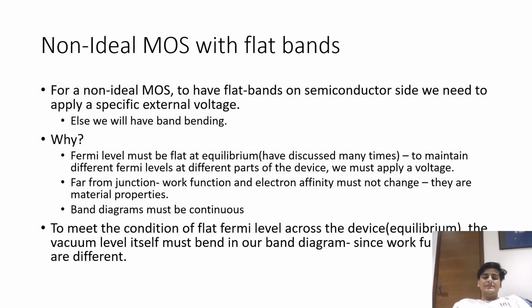Why is this the case? This is the case because if you have a low Fermi level at the metal and a high Fermi level at the semiconductor, for example, keeping a fixed vacuum level so that your phi m and phi s expressions are able to match, what that essentially indicates is that electrons are more comfortable being pulled towards the metal from the semiconductor. So essentially, there is a tendency for electrons to move from the semiconductor towards the metal.